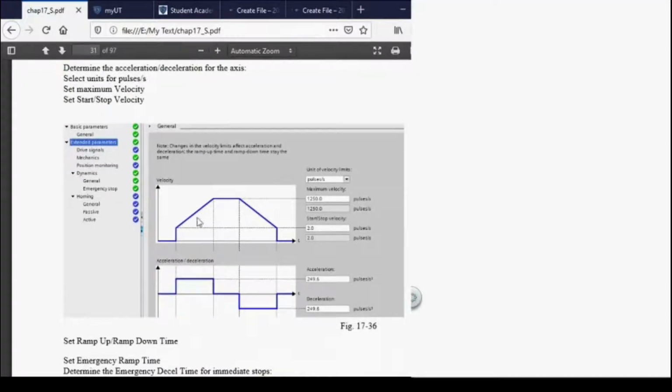Now when you program these steps here, you notice that you have to go off of 0, because 0 is not a valid speed, and you have to program in an acceleration time, a speed, a maximum velocity, and a deceleration. So you have to program these variables in. Now this is something that you just have to try if there's not something already recommended. Fortunately for you, they've already been implemented, and these numbers are already in there, and they work.